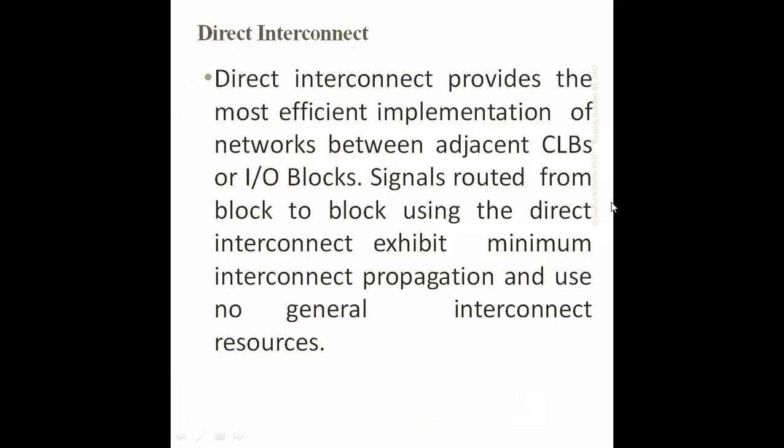Okay, that is the general purpose interconnection. Second is the direct interconnection. Direct interconnection provides the most efficient implementation of the network between adjacent CLBs and IO blocks. Purely, this interconnection switch is interconnecting between the IO block as well as the CLB.